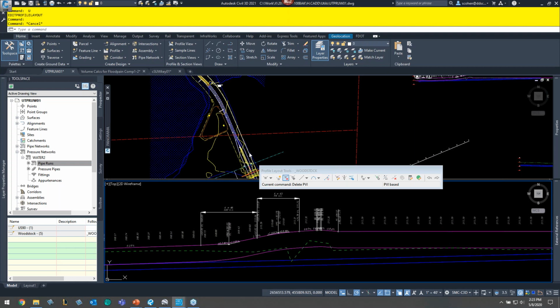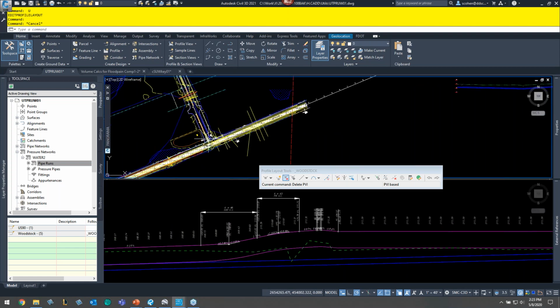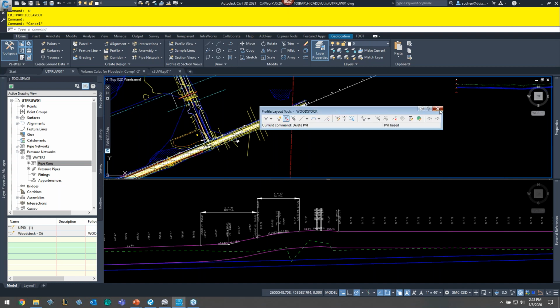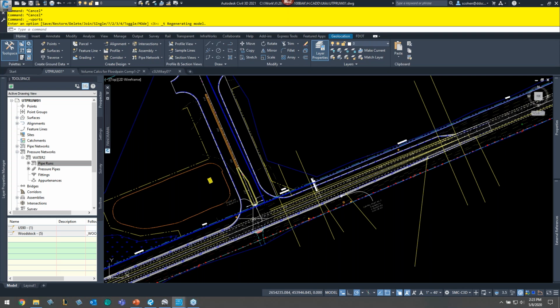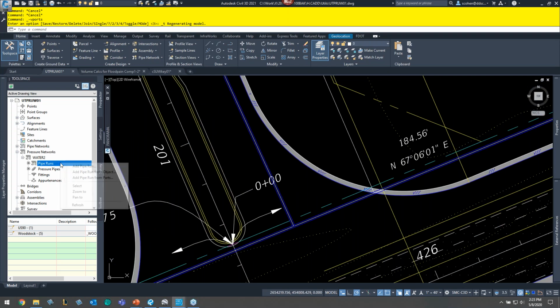All right. Now, can they be broken? Like I said, it looks like in some cases it might be able to, but again, once we kind of learn these tools and they work out all the bugs and fixes, it's all new, as with anything in Civil 3D. They'll work out the quirks and it'll work really, really nicely. Again, it's 1,000 times better than what it used to be as far as doing them from before. Okay, so again, those pipe runs are just really, really useful. Again, you can just have one, and then you simply right-click here, and it can be from objects, from parts, you name it. It can all be linked in that sort of way. All right.